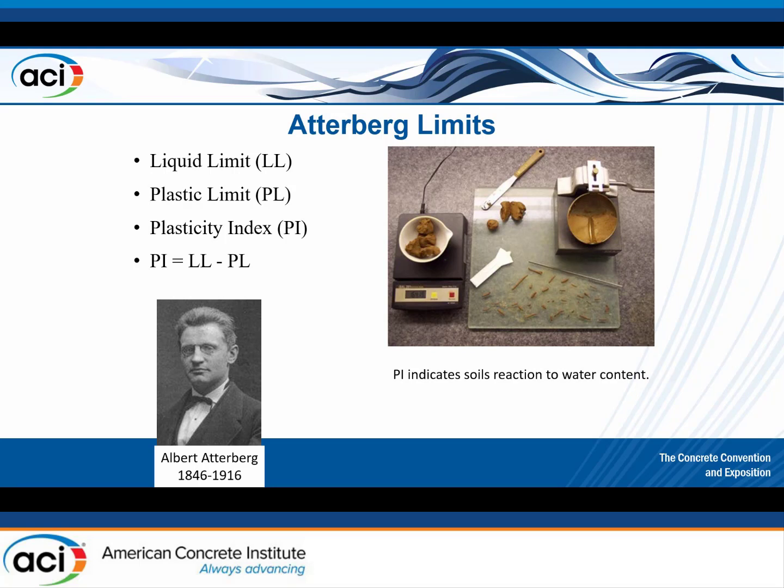Again, the difference between those is what we call the plasticity index. If we have a very low plasticity index of, say, 3, 4, 5, that's like a sandy material, right? Water doesn't really affect it. I'm from San Antonio, Texas, and if you go east of I-35, you can have PI values that reach 70, 75, even 80. That is a highly, highly plastic soil.